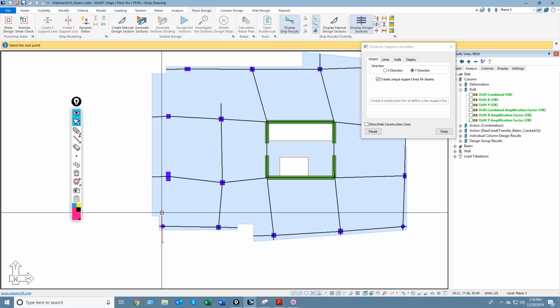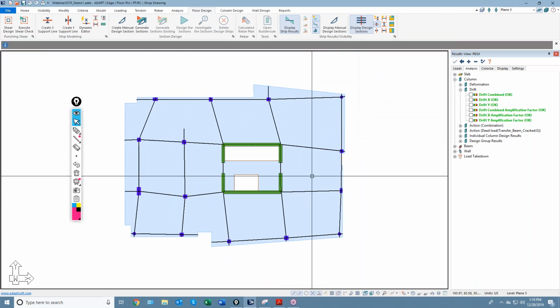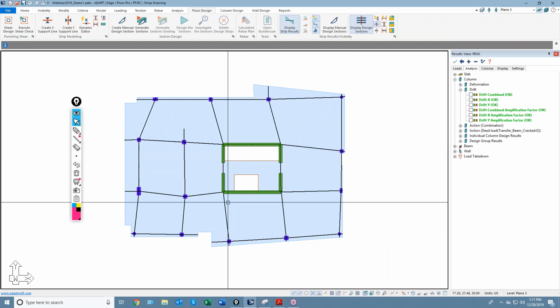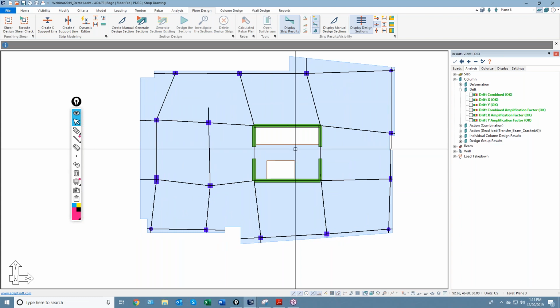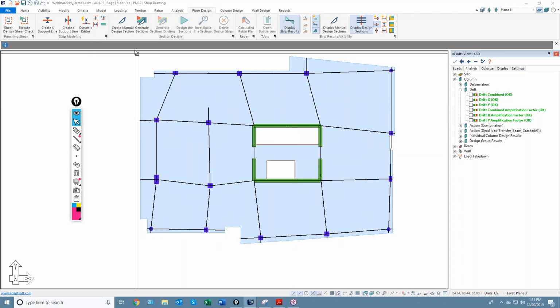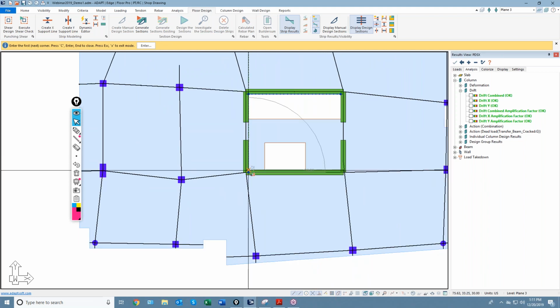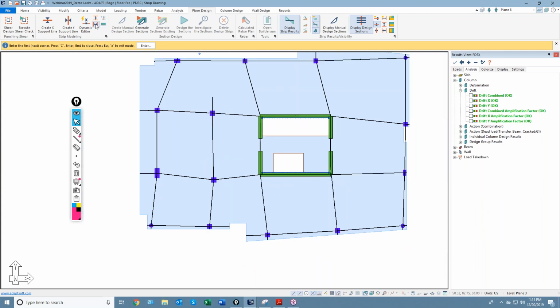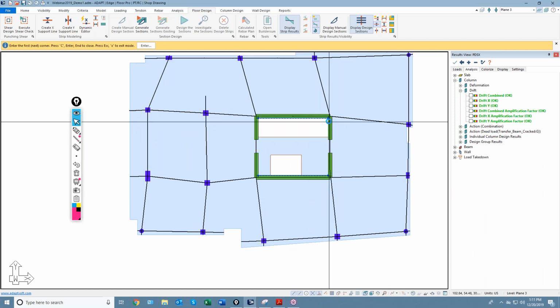Okay, and then we'll do the last set of columns here, and that's the generation of support lines for this example. Now, I want to avoid having the cuts go through the openings, so I'll use an X splitter, and the splitter I'm just going to add along this path and over here along this path. Oops, let me back up. I'll just snap on the corners of those walls, and then I'll use Y splitters to bound out the other direction.